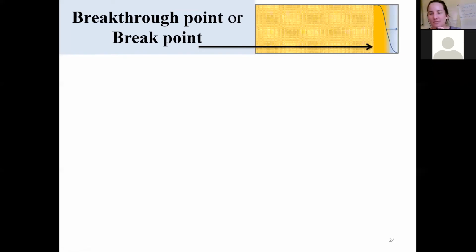Okay, once we have this velocity, as we mentioned, there's a certain time at which breakthrough will occur. So a certain time when the first molecules here will start to reach the end of the filter and they're not going to get adsorbed, they're going to start coming out of the system. We need to know this time because this is the time when we can operate the filter. So we're not going to operate the filter until it's completely full, but we're going to quit using the filter when it's no longer helping us reduce the air pollution.